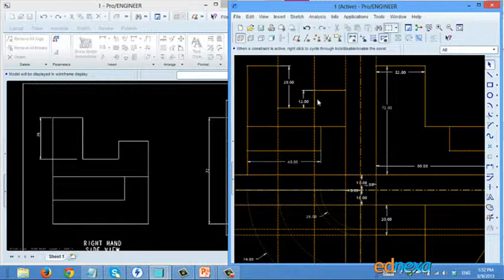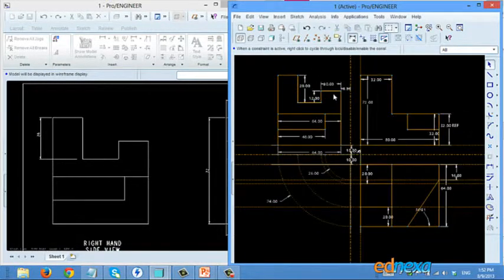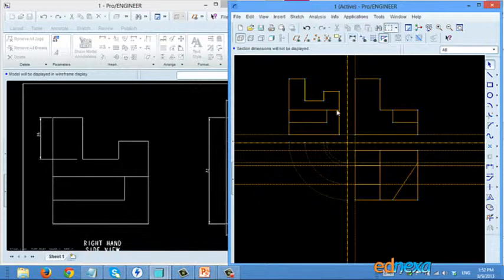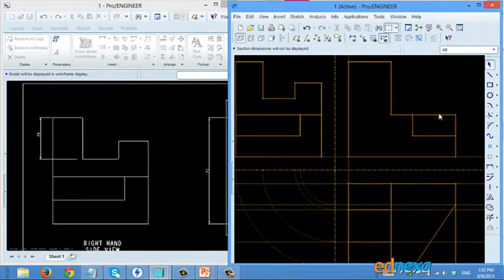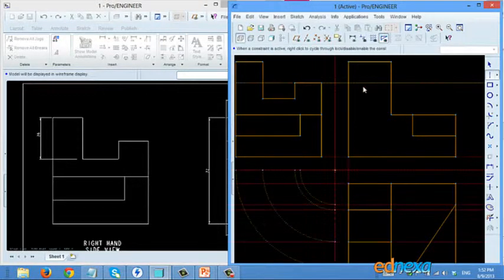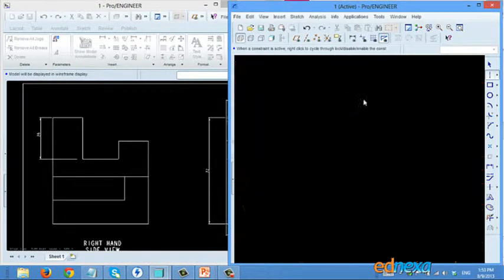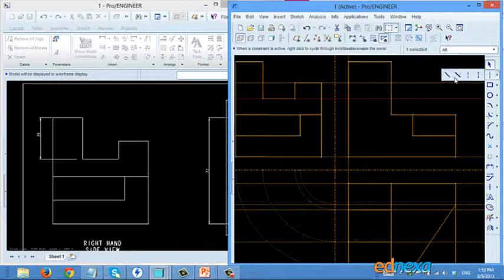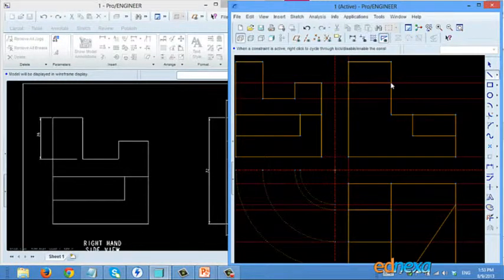So now we got both the hidden lines which are required in the front view. So we'll now project this line and this line here, and we'll draw two lines which are hidden.